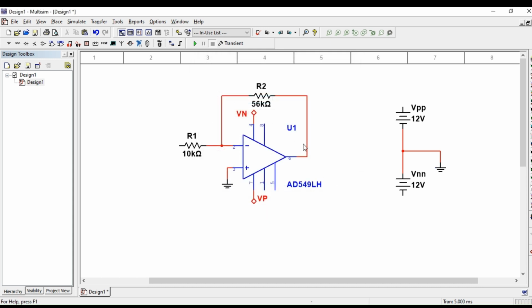Next, we need to use these connectors here also. So I will copy this one. Let's take positive first, Control C, and then use it here. It should be noticed that it has created a unique name for this connector, but we have to make sure that this name and this name are the same.